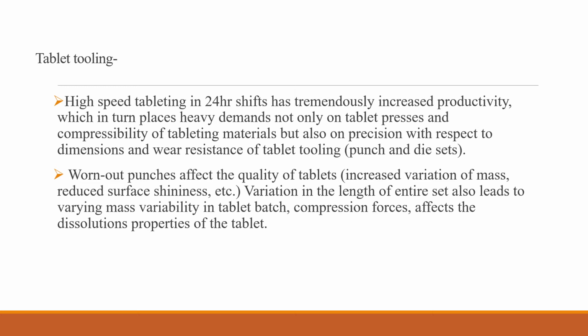Simple thing. Next point is worn out punches affect the quality of tablets, like increase of variation of mass, reduced surface shininess. Next is variation in length of the entire set, that also leads to variability in the tablet batch. Compression forces affect the dissolution properties of the tablet.